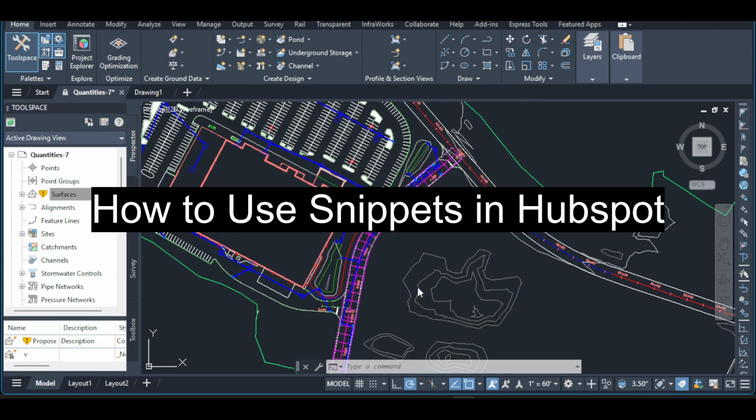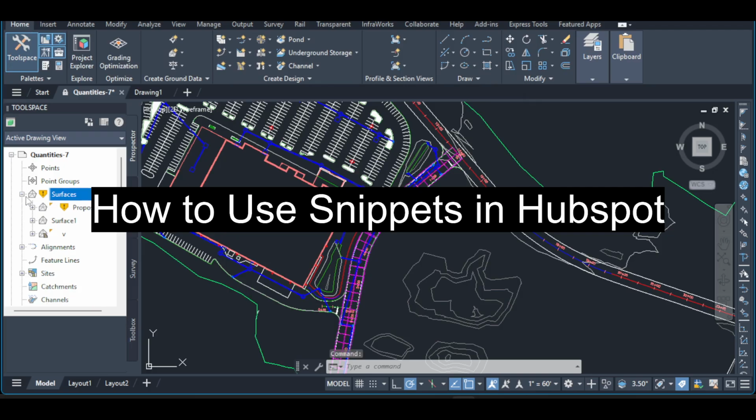Boundaries let you control the limits of the surface, for example, to clip away triangles outside your project area or to exclude interior regions like ponds or building pads. Pick the option that matches your data source, review any prompts or dialogs for file paths and formats if applicable, and confirm your choices. With your inputs selected, click OK to generate the surface and review it.